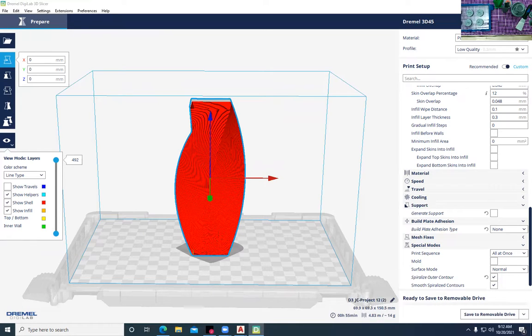With the linear oriented projects, they worked out really quite well. As long as we didn't have any big curves, as you can see with these projects, they came out really quite nice. I also found that if I use a good build plate adhesion, it helps create a base for the vase. You can look at creating a raft or a brim for that.